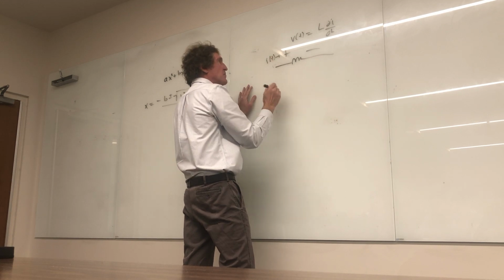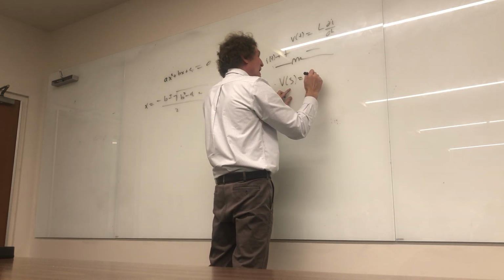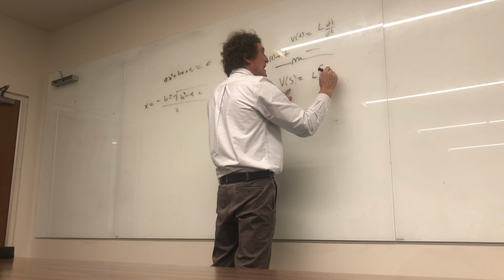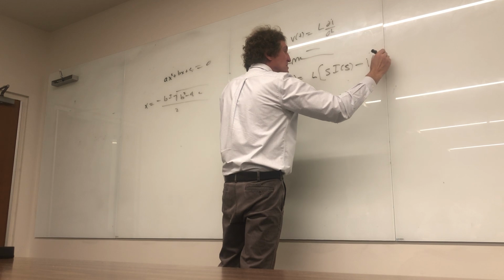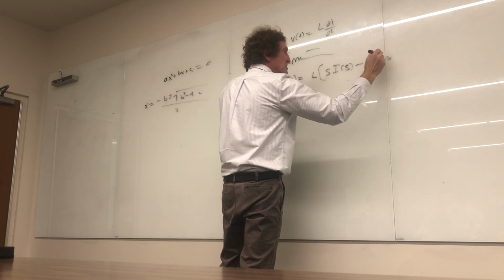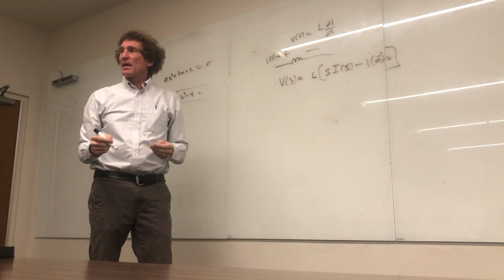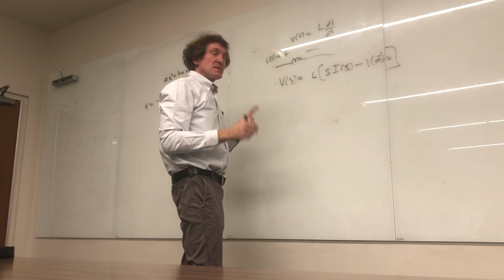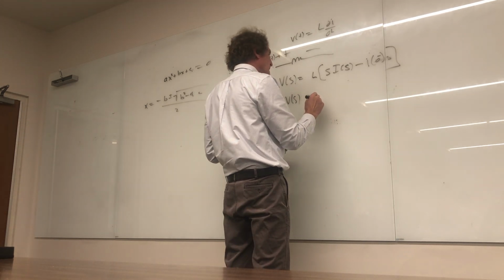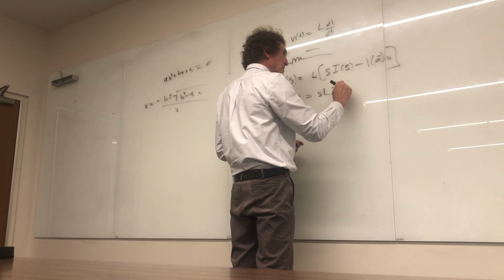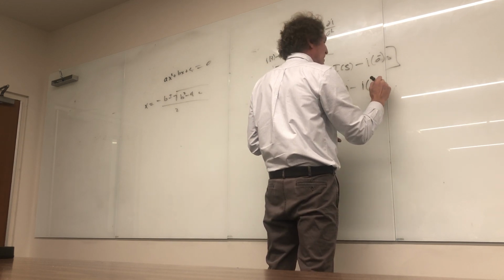Once I take a transform of that into the Laplace domain, I get V of s is equal to L times the quantity s I of s minus i of t at t equals 0. Or just put 0 in here. They put 0 plus, 0 minus, doesn't matter. It's the value of the current at t equals 0. Now, typically, you say V of s is equal to s times L times I of s minus I at 0, times L.